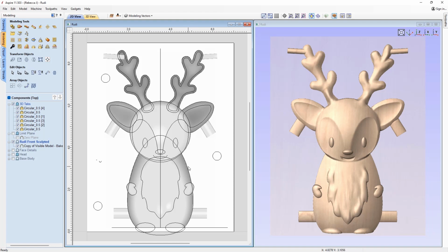So what we want to do is tell the tool to cut a little bit past 0, and the only way for us to do that is by implementing a 0 plane, or in this case I call it a limit plane. I call it a limit plane because I'm basically naming it that as a limit for where the tool is going to go. Okay, and so it's essentially just a 0 plane.